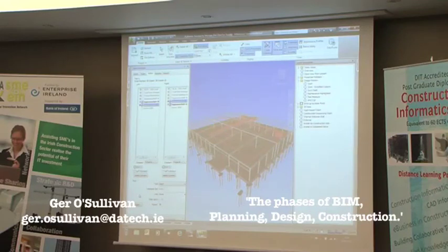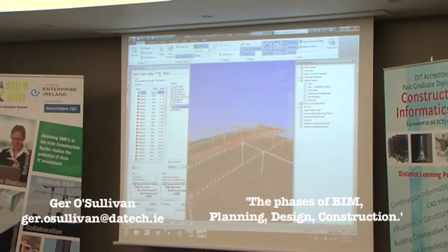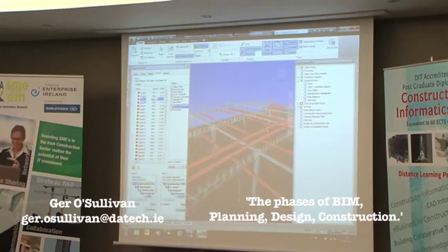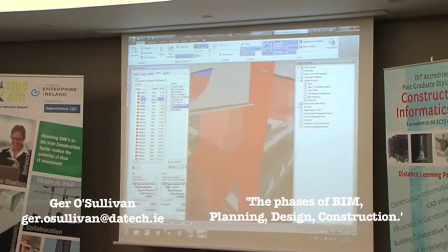So how do I see those clashes? At the moment, we're seeing the whole model. Well, it will give you them in an image or a clash by clash option. So very quickly, we can then see the clashes. We can use the model to jump from clash to clash. So you're seeing them like that. You can then decide, reviewing, is this a new clash? Is it an active clash? It will obviously change colour. Is it reviewed? Is it a clash that I've approved? In this case I probably wouldn't approve that, but I can do it if I wanted to.